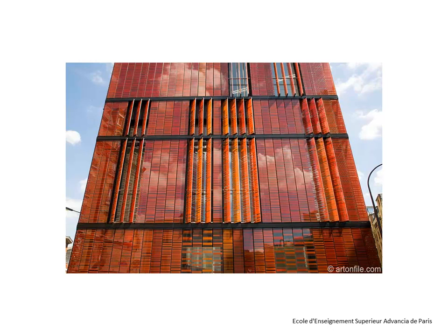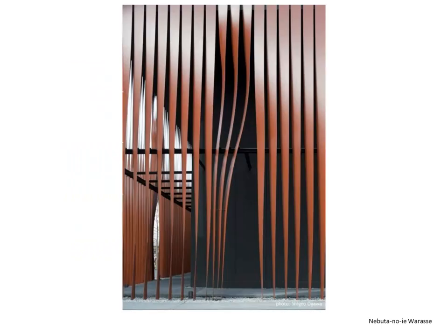Typically, on the east-west sides of the buildings, we want Louvers moving vertically to shade the sun as the sun path travels in the day. They're either moved by the occupants of the building or they're mechanically actuated. Then typically on the north-south sides of the building, we have horizontal Louvers moving up and down. Alex, am I right? Okay, I hope so. Otherwise, it's the opposite of that, right? There are only two choices.